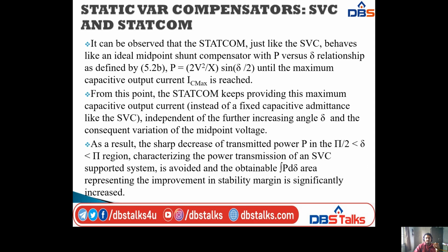From the observation of the diagrams, the STATCOM, just like the SVC, behaves like an ideal midpoint shunt compensator with a P versus delta relationship. I already explained this concept in the objectives of shunt compensation, and I also discussed it there.